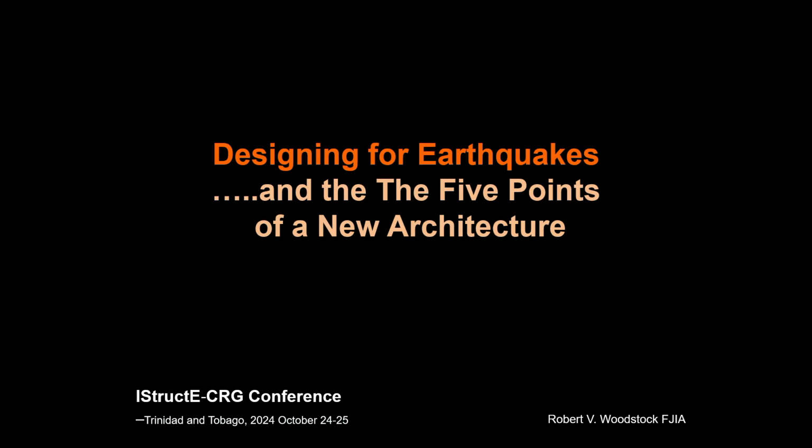Following on from Tony, I shall begin by repeating what Tony has said to me and emphasized many, many times. The most important architectural decisions that affect seismic performance are the critical decisions that create the building's configuration, its size and shape, and for structural purposes, the nature and location of resisting and non-structural elements within it.